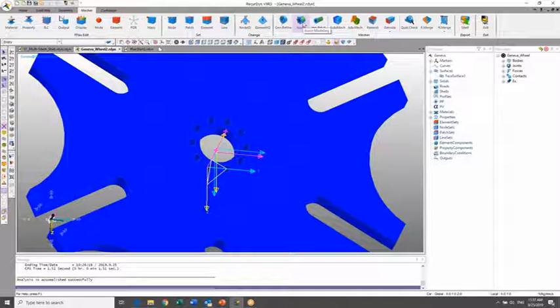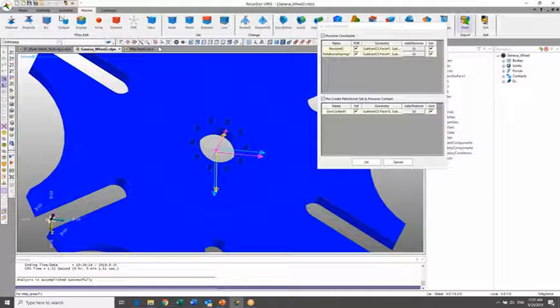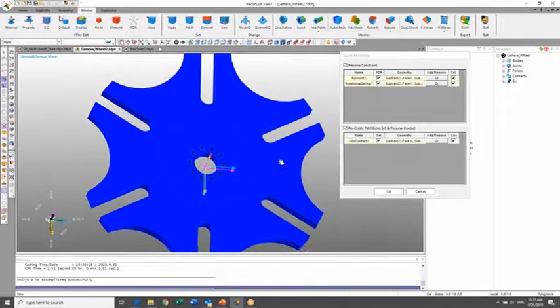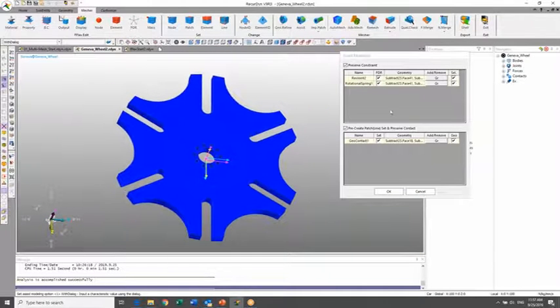I'll click this assist modeling, again working from left to right as a standard process. And this is where, because I'm using this G Manager, it's trying to preserve the joint, preserve the spring damper, and preserve the contact. So this is where you see how it's trying to preserve that.